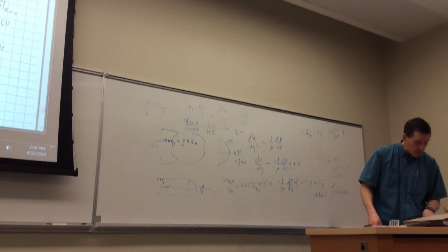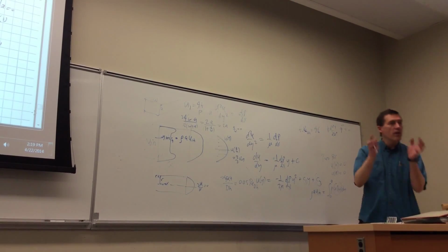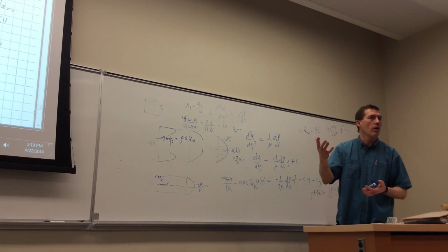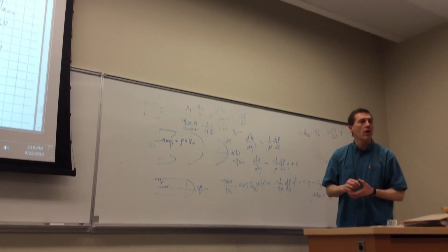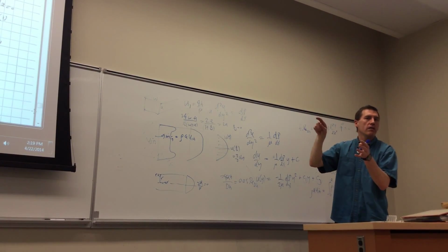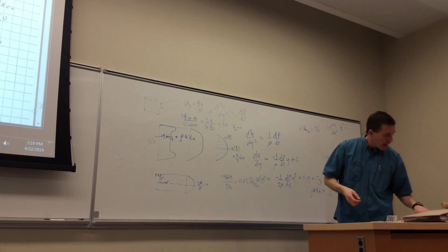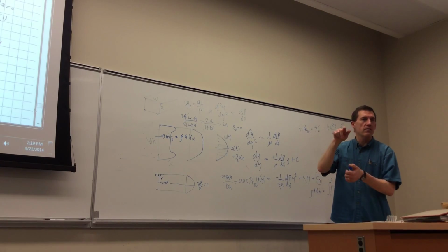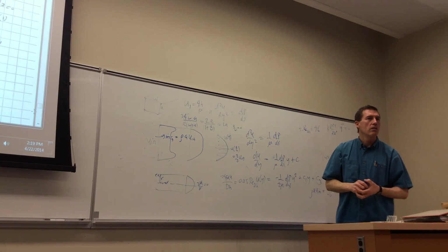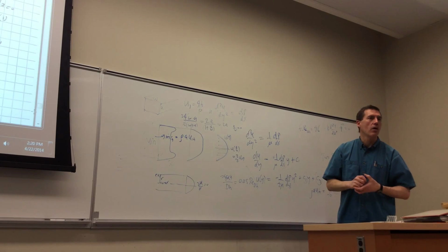There is a class of problems, and I've done this before on final exams or term tests, where you give the equation U of y and T of y, and you ask for the heat flux at the wall or the friction factor or shear at the wall. What you're asking is for people to know that tau wall is equal to mu dU/dy, or mu dU/dr with radius, and that the heat flux is minus k dT/dy at y equals the wall. So you're just using the basic definitions of the tau wall and the heat flux at the wall.